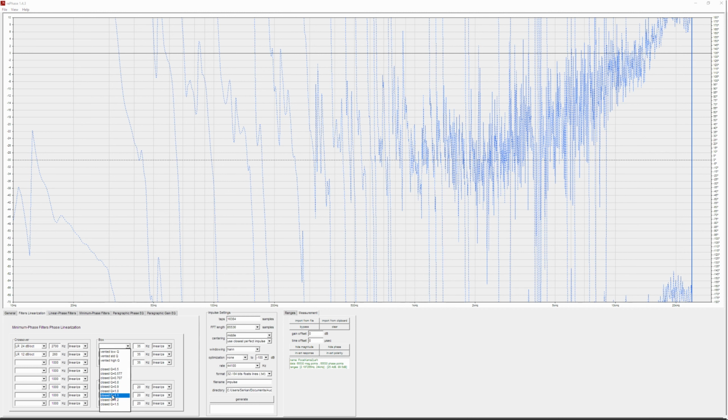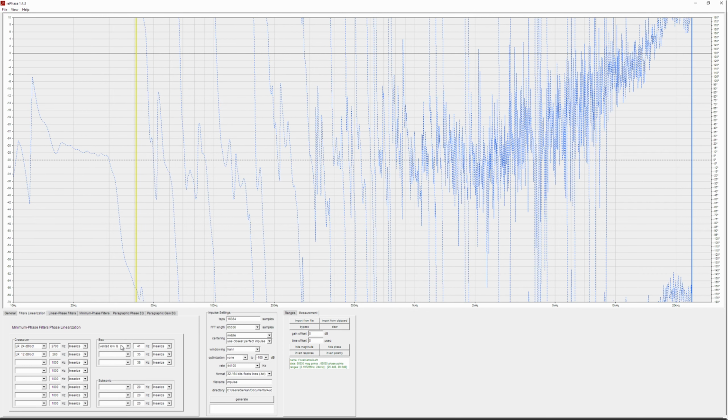Again, thanks to Stereophile's report, I know that my combined port frequency for the speaker, which in fact has both a rear and a front port, along with an additional passive woofer, is at 41 Hz. Low Q vented seems to be the best match among all these.